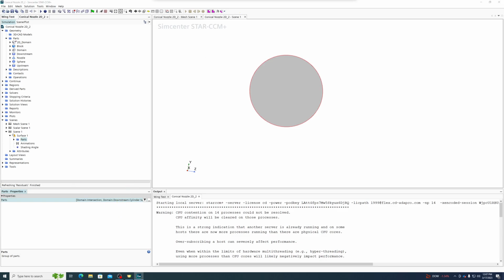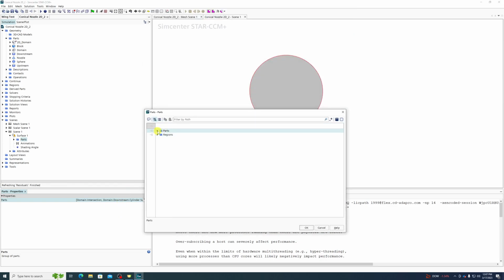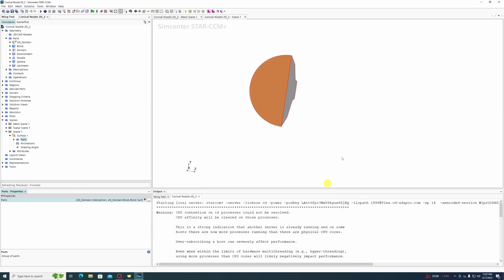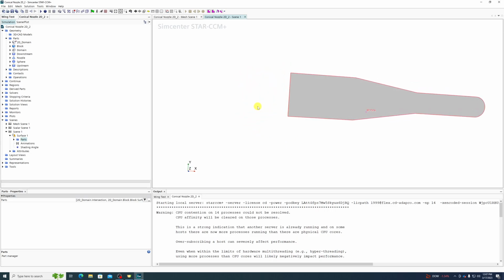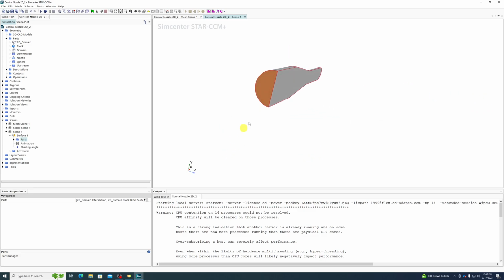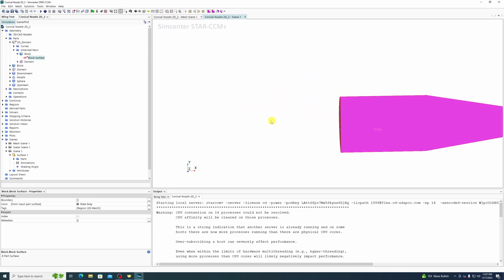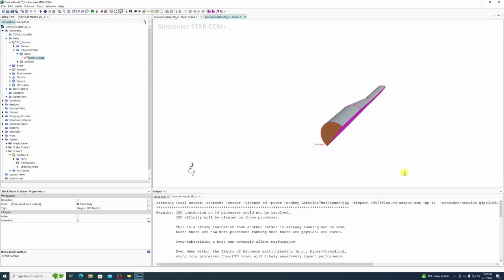Oh, did that not work? 2D domain. There, we cut this in half, right? So the question, some of you ran into this, is what are we simulating here? You might think, oh, we're simulating a cylinder. We're not, actually. The software knows that this is the shape that it had originally, but what it's simulating is entirely just this flat surface right here.